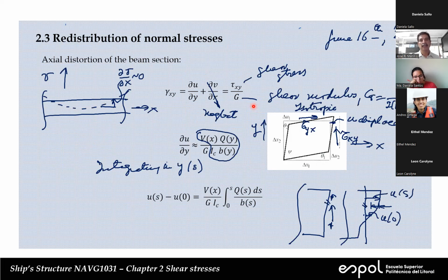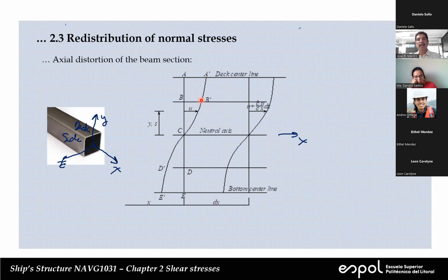Okay, here I have du dy. We have to be careful. And this is the shear strain. Here I have du dx, and this is the normal strain, because this fiber, the original length was dx, and now it has elongated. And this is the strain.